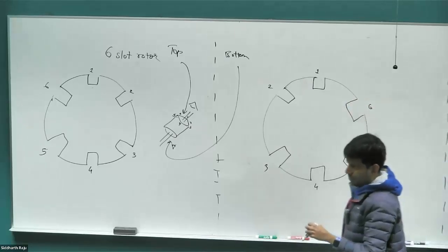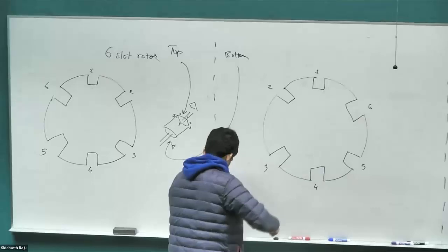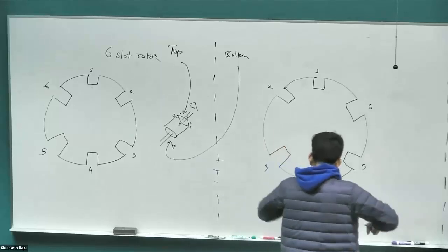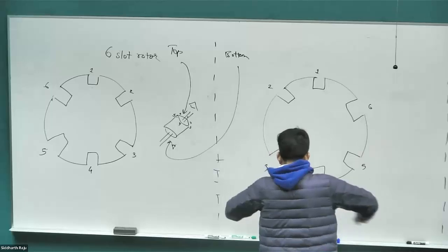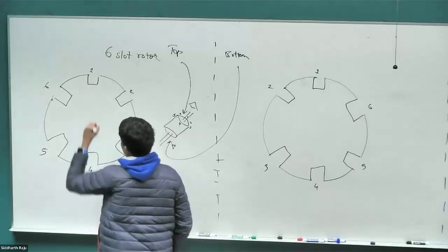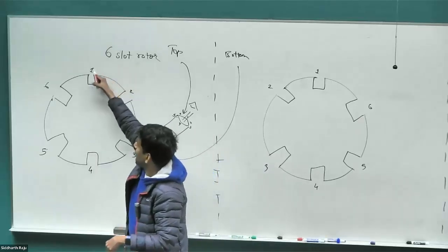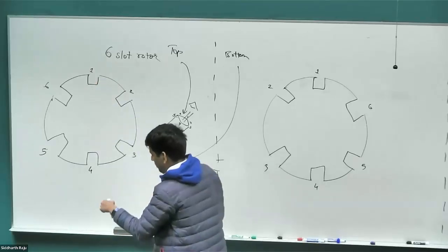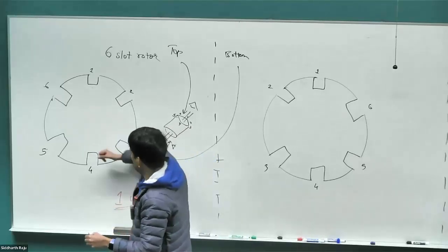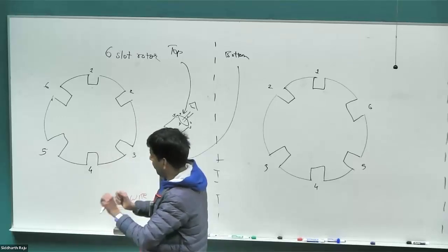So we're going to track how these windings are wound going from one slot to the other. Let me see if I can use different colors. So let's start off with the first conductor. This is again the top view. The first conductor is coming from the back of the board and coming outwards. And then we take that same wire. It's just a single wire. Throughout this winding diagram, there is just one wire, right? The way I'm drawing it is as multiple different conductors, just so that you can visualize how this wiring goes around. But it's just a single wire that the machine winds multiple different times. At no point does the wire break.